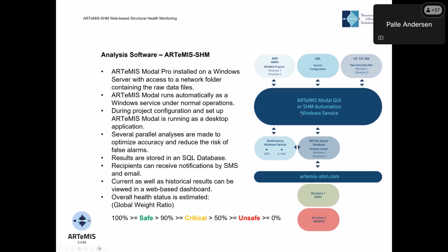And what this service is doing then is monitoring a folder somewhere on your network. When new data is arriving for a structure from the data acquisition system on the structure, then this data is loaded into ARTeMIS, it's being analyzed, and it's being saved. It is saved to a project file, but it's also saved to an SQL server database where the results are then lying and ready to be viewed by other tools.